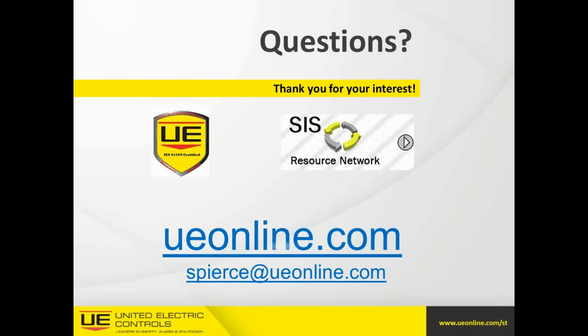And when that happens, you have that human interface, which is required in some industries. Outside of that milliamp output, you have that digital output that indicates, hey, wait a minute, I know you're still getting information from that 4 to 20, but something's wrong. And it could be anywhere on this device that you get that.